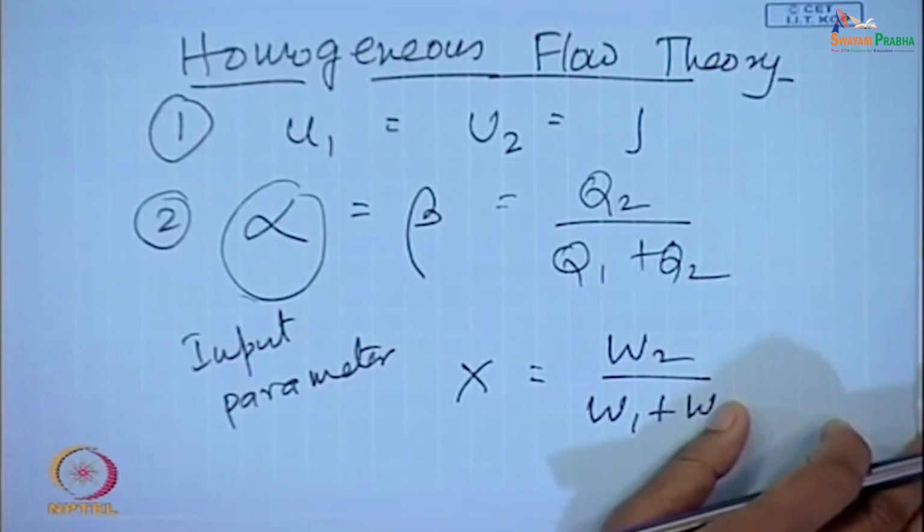This has to happen. Unless there is thermodynamic equilibrium between the phases, there will be heat transfer, momentum transfer, energy transfer, mass transfer. Moment those things happen, then under such circumstances we cannot have the homogeneous flow assumption, because the entire thing has to be uniform throughout.